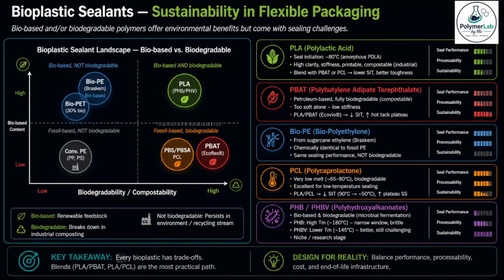The bottom line on bioplastics: they can seal, but every option involves some trade-off: cost, processability, narrow sealing window, limited compostability infrastructure, or performance limitations at temperature extremes. Blend strategies, particularly PLA with PBAT and PLA with PCL, are currently the most practical paths to sealable, compostable packaging.